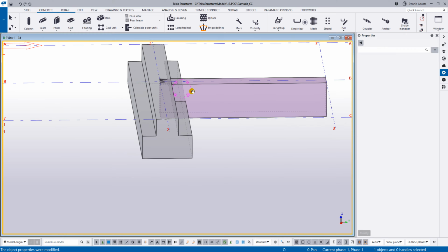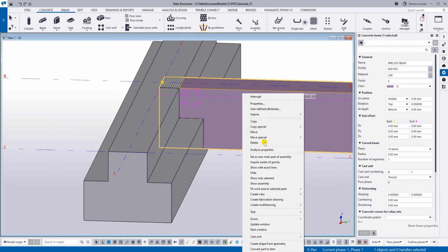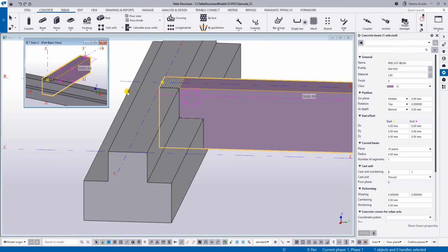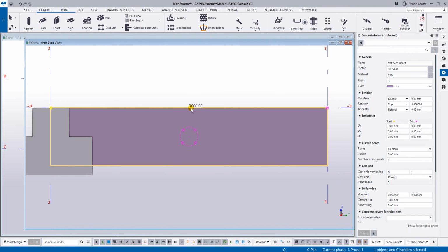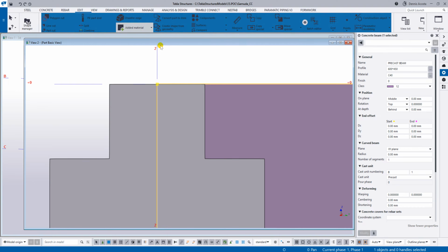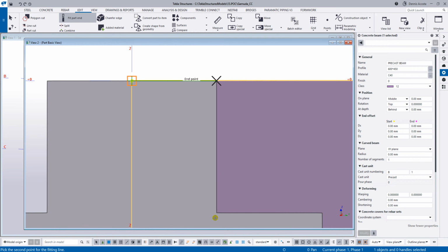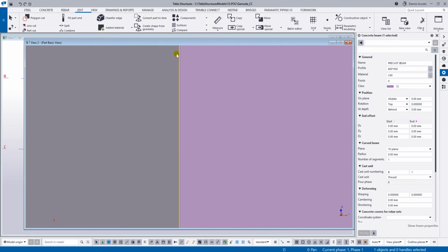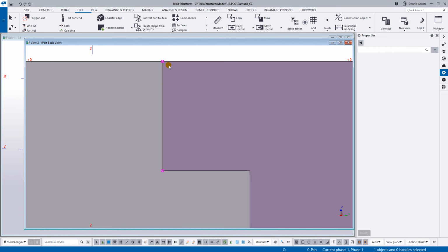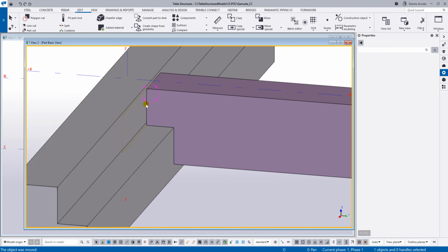The first thing to do is this. We need to cut this one according to the surface of the outline. So here I need to create a 3D basic view, and then Control P. Here I'm going to cut a 10 millimeter gap. So edit, and then fit part end, and then click here, 1, and then this one, 1, and then 2. So that one is cut, but I need a gap so that I can now move this one, maybe I'll put a 20 millimeter gap. There you go. So look, that is cut, 20 millimeter gap.